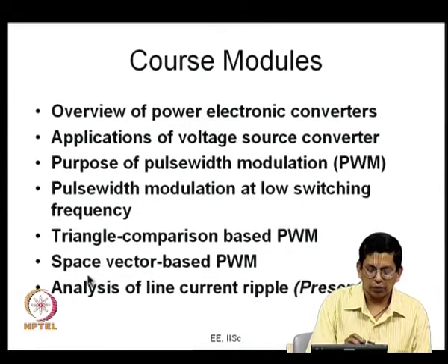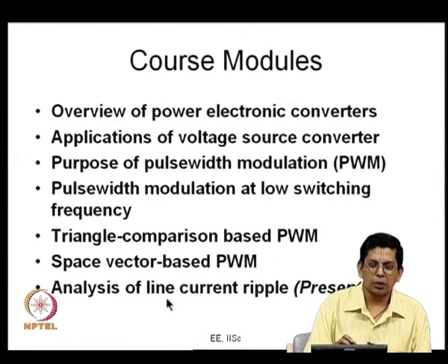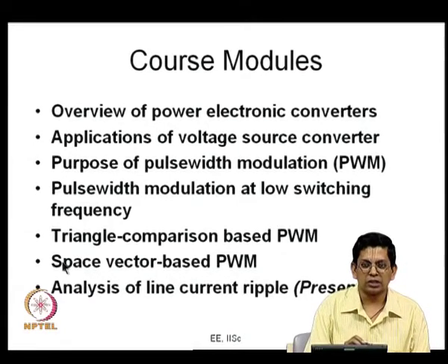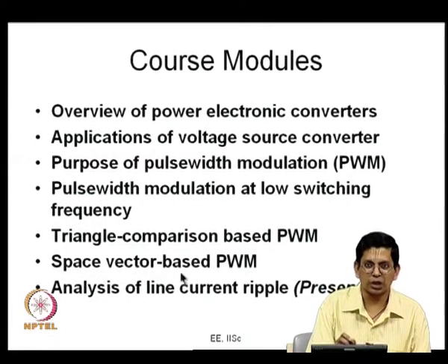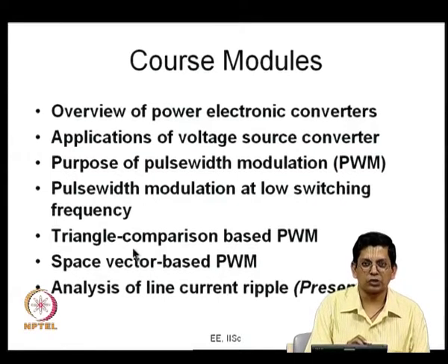And this is an alternative approach which is space vector based PWM, and we showed that the space vector based PWM is more general than triangle comparison PWM. Many continuous PWM and discontinuous PWM methods are there, and those PWM waveforms can be generated either using the triangle comparison approach or the space vector approach. There are certain advanced space vector based bus clamping PWM techniques. The PWM waveforms pertaining to those advanced bus clamping techniques can be generated only in the space vector approach and not using the triangle comparison approach.